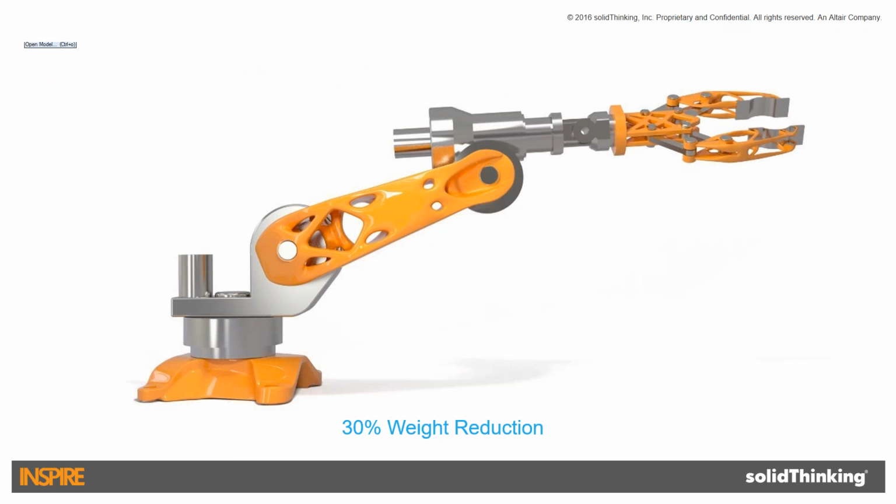So in this example, this robot, we took 30% of the weight out of it. You can get away now with smaller motors to do the same type of performance you had before, and use less energy, so it's more cost effective. And that's really the power: companies are able to make parts that are lighter, that are stronger, and actually last longer, because topology optimization evenly distributes stress throughout your component. Typically that results in much higher fatigue performance.